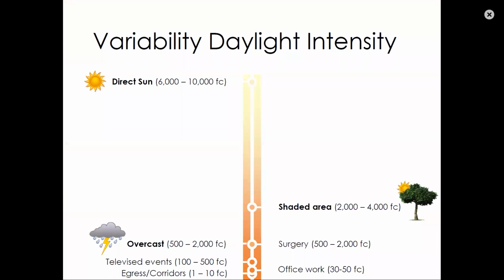So to further illustrate the variability in daylight conditions, let's look at typical light levels of interior and exterior environments. Most recommended interior light levels are between 10 and 50 foot candles, while exterior daylight conditions can vary between 500 and 10,000 foot candles. So the range of daylight conditions makes it particularly difficult to use passive or fixed shading systems.